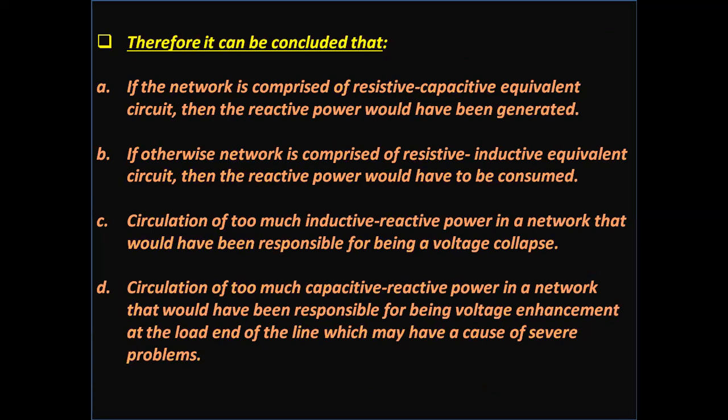Therefore, it can be concluded that A, if the network comprises a resistive capacitive equivalent circuit, then reactive power would be generated. B, if otherwise the network comprises a resistive inductive equivalent circuit, then the reactive power would be consumed.